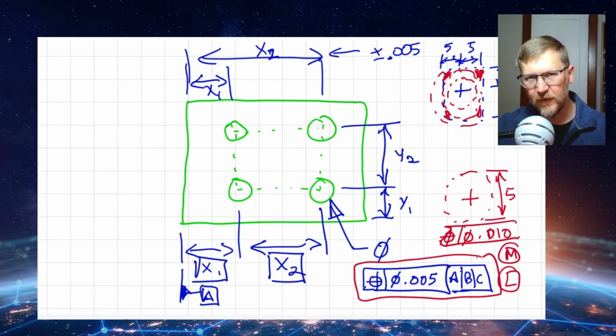And of course, if you're talking about a hole, the maximum material condition is when the hole is as small as possible, which basically means if that tolerance applies under those conditions, well, if the hole's a little bit bigger and you go towards the larger size of the tolerance for the diameter, say 5/1000ths, well, now I can accept that much more uncertainty in the position of the hole.